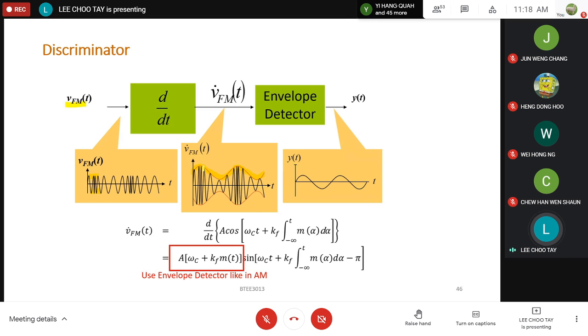All right, and then the carrier, again, for double sideband full carrier signal, the carrier frequency is constant. But in this case, the carrier frequency is not really constant, but the envelope is similar to the double sideband full carrier signal. So we just want the amplitude information, because now the message is all contained in the amplitude already.